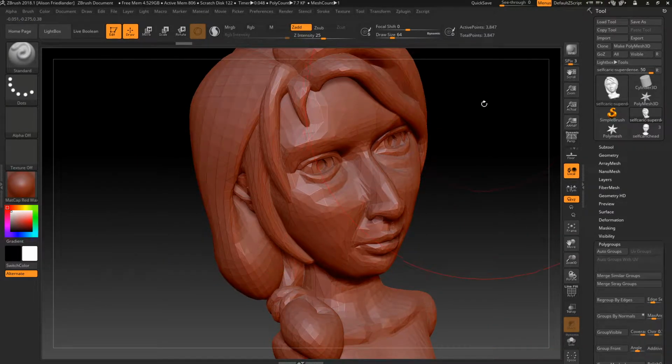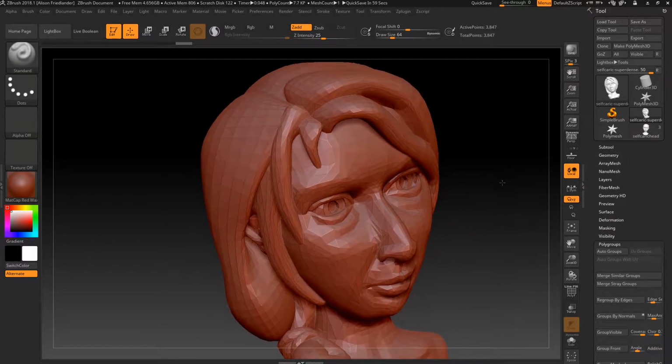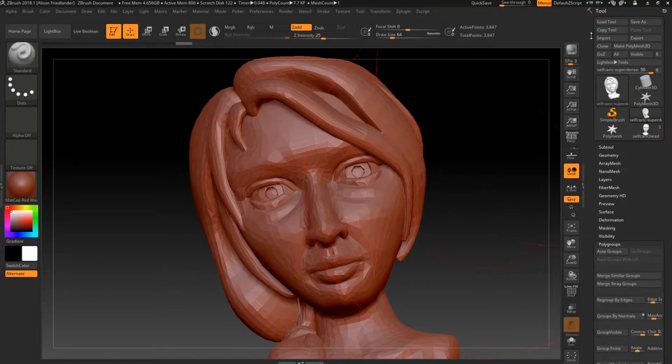All right. Another fun tidbit, in terms of order of doing things: in my experience, it usually makes sense to reduce your meshes before trying to Boolean them together. It'll just make your life easier and faster.